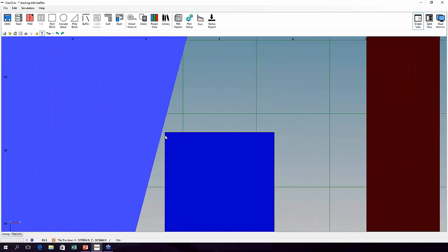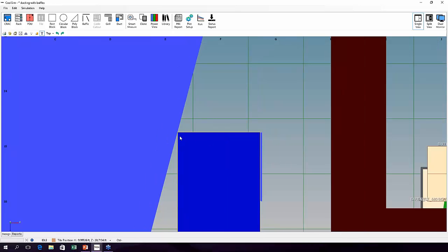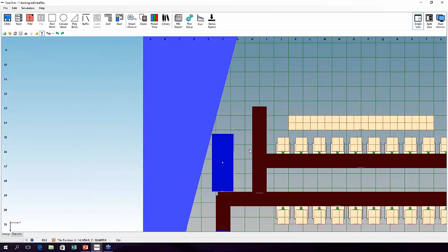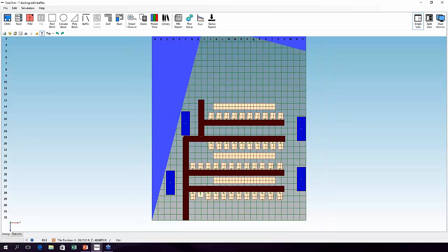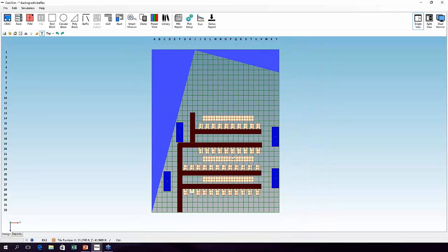This is a tough one for a mesh to generate right there. It's actually a little better if there's a gap. If I had this tight against that angled wall, that's even harder for the mesh to generate a good mesh in that. And mesh quality does make a difference and will cause some issues to occur sometimes in solve. That is when you may want to use a fine or a medium mesh.